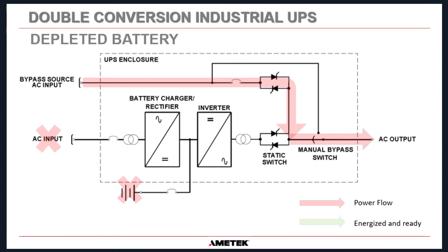So our system actually trips a DC input breaker on the UPS, and just before it does that, it sends a signal to the bypass source static switch. It says, okay, you're in synchronization with the inverter, transfer to the bypass supply and transfer the loads to bypass, and then it trips the breaker and the inverter shuts down.